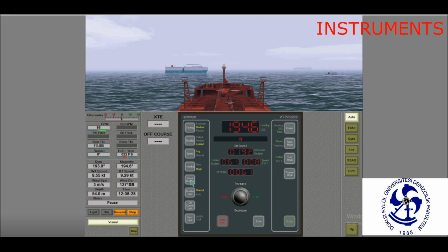Controller. Key for setting the ship's counteraction coefficient in turning into a set course. Rudder limit. Key for setting the rudder angle limits, used for selecting the parameter input mode, manual or automatic. Off course limit. Key for setting the limit of the current course deviation from the set course. Also, we have two general function keys: LM acknowledge, and the enter key for confirming data input.